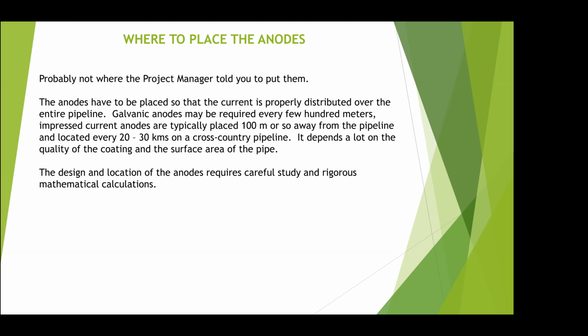And if you light one candle, you don't see very much. But if 100 people light candles and stand around the walls, you'll see the whole place illuminated just from the candles. And that's pretty much how we place the galvanic anodes. We do a calculation to show how far it will stretch and how it will deliver the current over its entire design life till it gets down to just about 20% of it being left. And we can then say, okay, on that basis, we need one every 50 meters, every 100 meters, every 10 meters, whatever it happens to be, depending on the conditions.